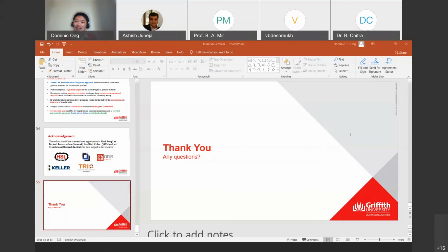Now, if you were to go to conventional design, I would say that 25 meters, you're probably pushing the limit for stone columns in soft clay. Basically, they worry about verticality, because there are a few projects in Malaysia where the contractor was involved in trying to replace pile foundations as well. I remember that anything more than 25 meters of soft clay, the contractors in general give up. They do not want to do anything deeper than 25 meters for stone columns. So that's my thought on it.